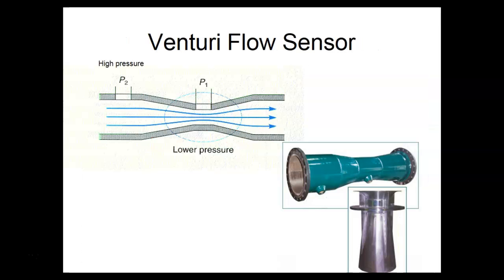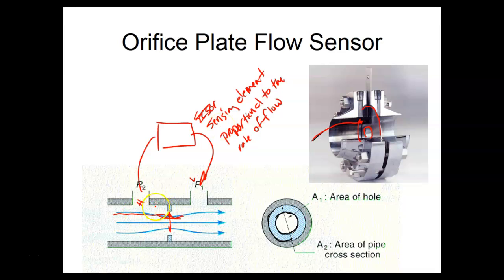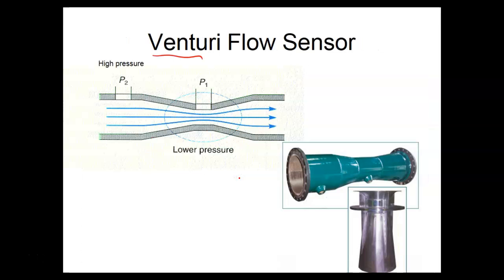This is basically what we use over in both our manufacturing lines. We actually use this technique to generate a vacuum. It's called a Venturi. This is a little more efficient than the orifice plate, because the orifice plate is going to create a lot of turbulence right in here. A Venturi has a tendency not to produce that. The flow comes over here, goes down, speed goes up, pressure goes down, and then it comes back and expands back out.